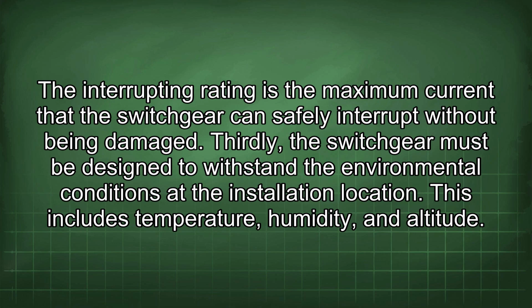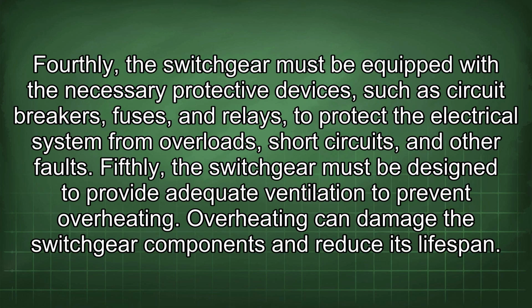Thirdly, the switchgear must be designed to withstand the environmental conditions at the installation location. This includes temperature, humidity, and altitude. Fourthly, the switchgear must be equipped with the necessary protective devices such as circuit breakers, fuses, and relays to protect the electrical system from overloads, short circuits, and other faults. Fifthly, the switchgear must be designed to provide adequate ventilation to prevent overheating. Overheating can damage the switchgear components and reduce its lifespan.